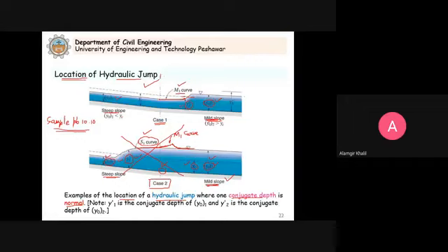And in here, you see that the hydraulic jump occurs here. Now we are looking for the location of the hydraulic jump. So now for this given problem and this associated figure, we say that this is the correct possible situation. We are interested that it will occur after the break. This is the break in the slope. The hydraulic jump will occur after the break, but at how much distance? This is now the next question that we have to answer.